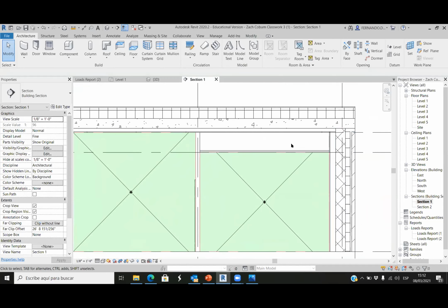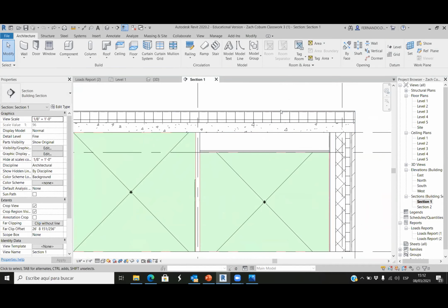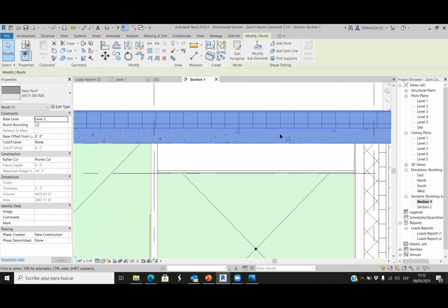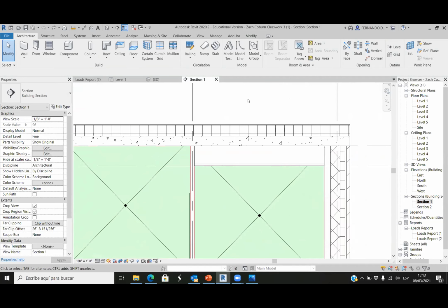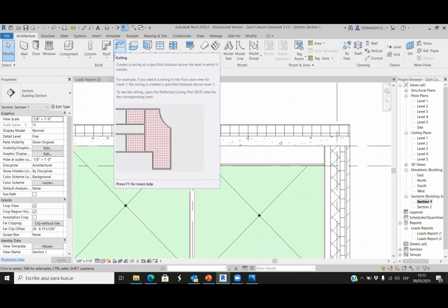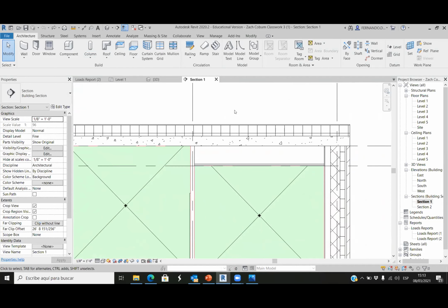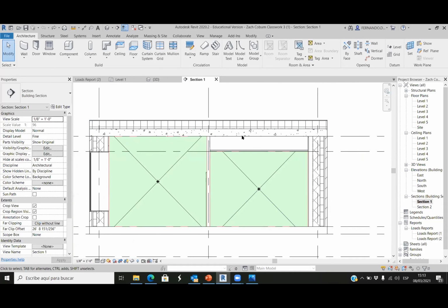Okay, so we can undo, and we can have this floor just with the concrete, the structural element, the thermal insulation, and then the waterproofing. And if we want an air gap in the false ceiling, we can use the ceiling option of Revit. I showed you how to do this last week. Okay, but don't do it twice. It doesn't make any sense that you have this false ceiling here and then you include the air gap and the gypsum board on the roof element. So make sure that we have, I prefer this option actually. Okay, so you can do this.